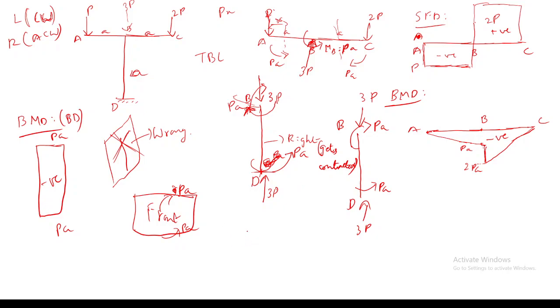Clear, right? So we did take the 3P in the reverse direction for BD. If you transfer the bending moment due to PA, do we need to take it in a reverse direction like that for BD? Yes, see, for both bending moment and all the loadings, you need to take the reverse direction for the BD member compared to this ABC member.